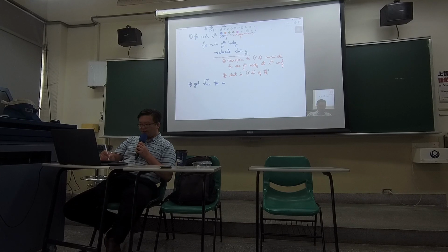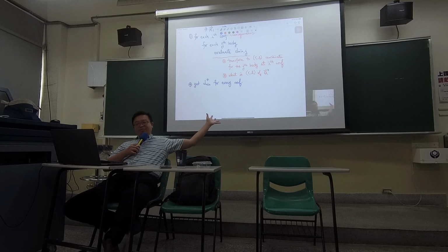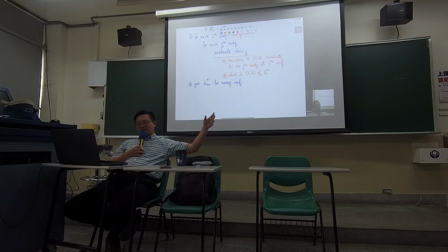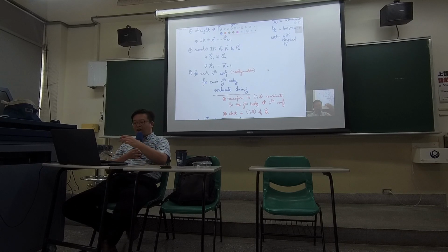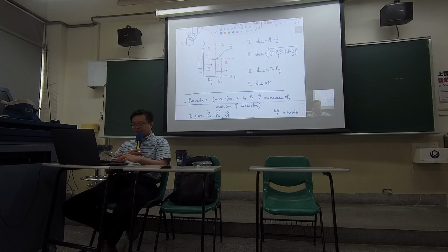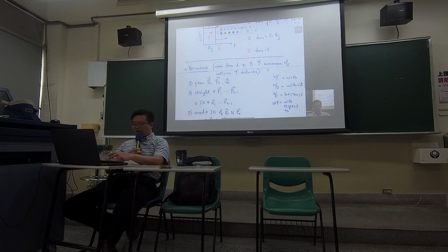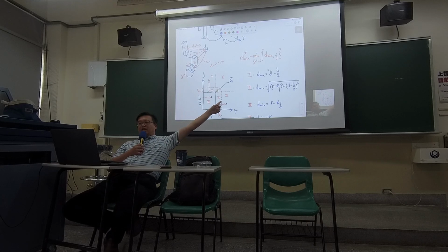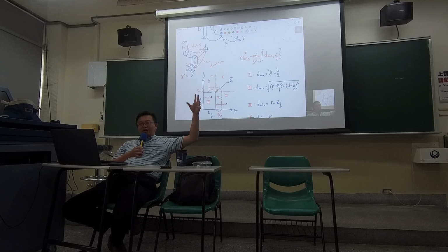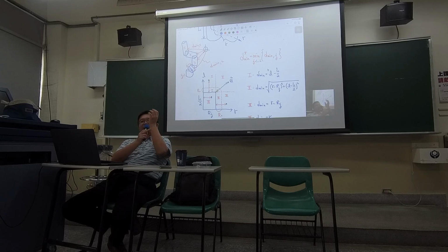for every configuration, because from the for loop, you will get every shortest distance. And for the ith configuration, the overall D minimum star is going to be the smallest one from the shortest distance between the obstacle and every part.